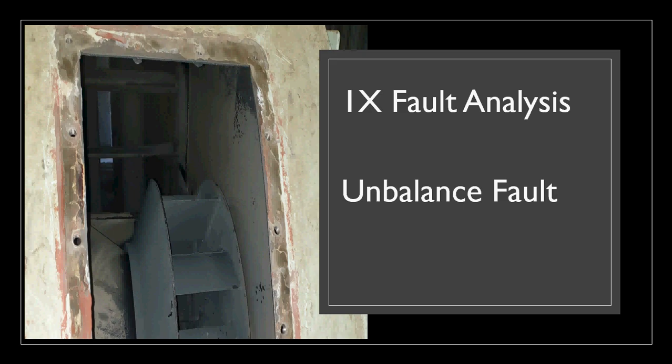1x is a very common pattern you can see in the vibration spectrum, and it's the most difficult pattern to diagnose because 1x could mean many things. It could mean unbalance, eccentricity, bent shaft, excessive clearance, even soft foot. We're going to talk about all these types of faults in the series of fault analysis. But let's start with the unbalance fault.